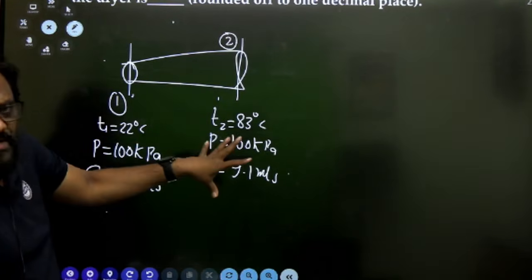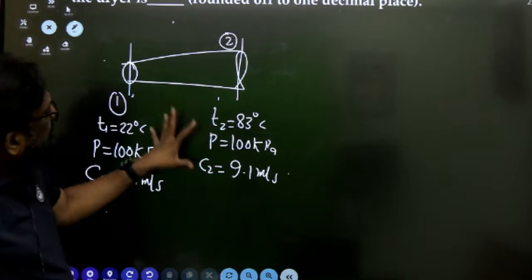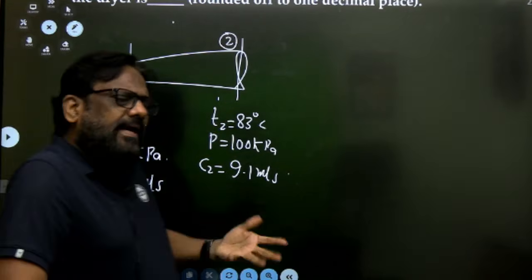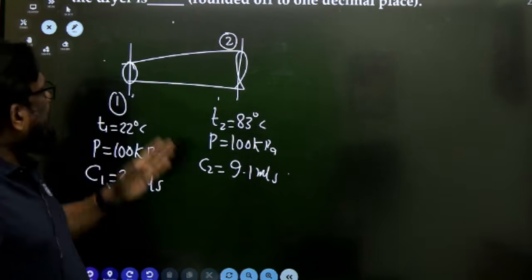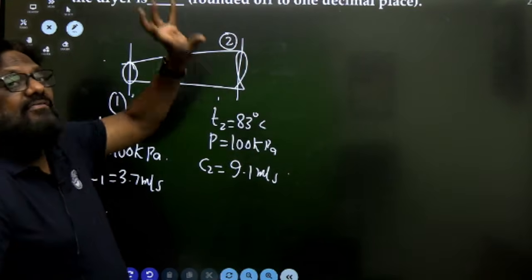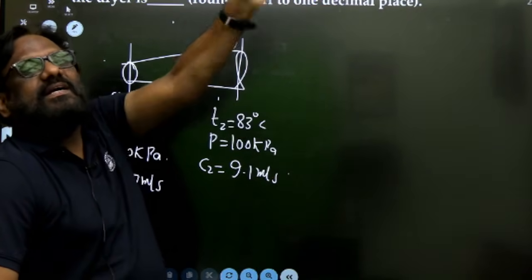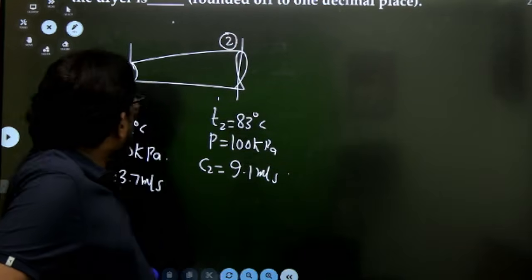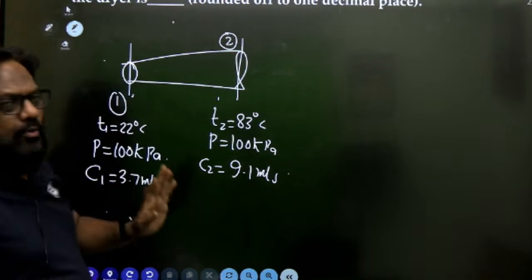We have supplied energy, so its energy increased. From here we can find how much energy was supplied, but do you think all the energy can be utilized? No sir. So what I do is I will calculate the increase of availability. The increase in availability from here to here, by the energy supplied, will be the second law efficiency. Let me repeat, sir. It's a flow process. Fluid is entering and leaving.